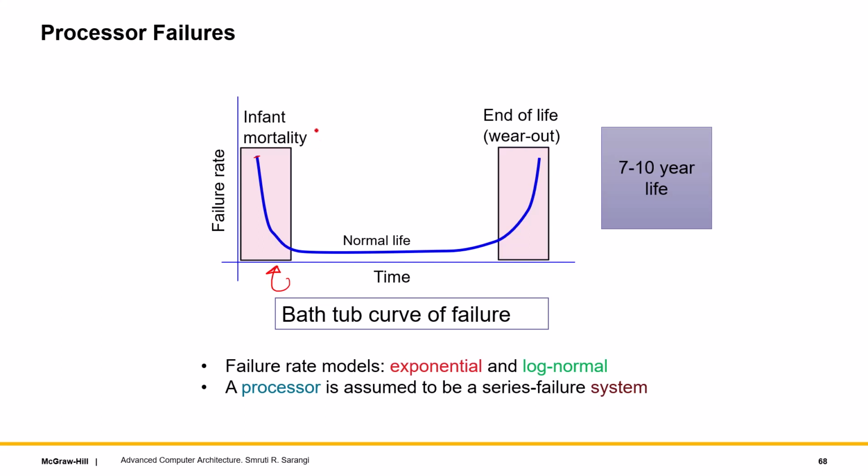What is burn-in? We have discussed this. After a chip has been packaged, in some cases before it has been packaged, it's taken to an oven. There you really raise the temperature and then you do testing over there. Then many of these faults become more visible, more prominent. They come out of the closet.